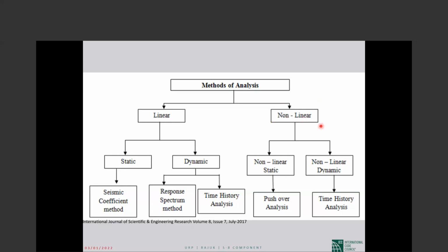But tonight we want to discuss the nonlinear static approach, and the approach that from the beginning the codes for existing buildings prefer, which is static. So static nonlinear is the main, the governing analytical method in the codes for existing buildings, and by far it is pushover.